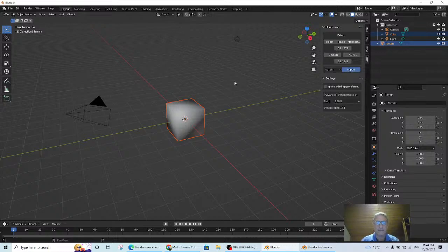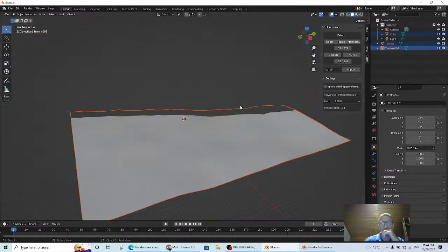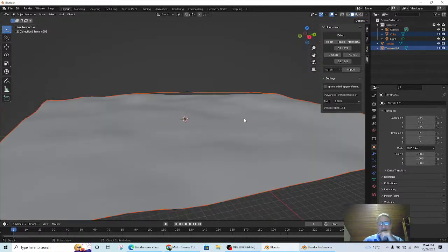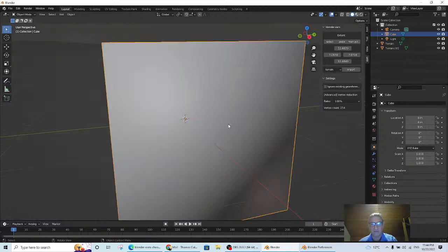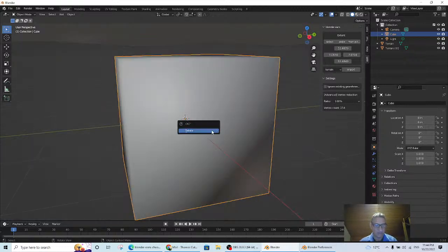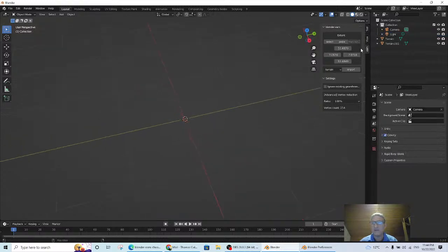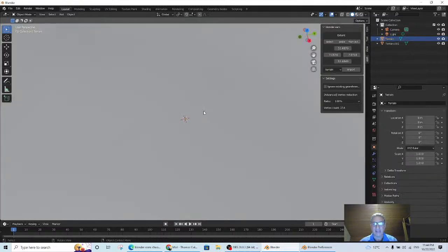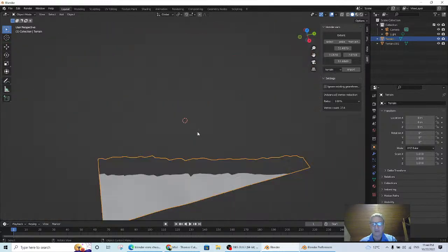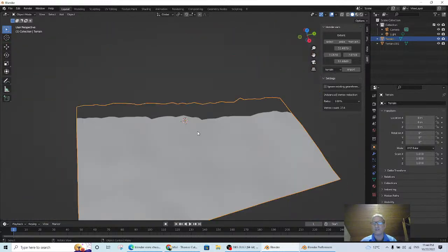And you wait, and the terrain should come in. You see it's spinning. So wait for the terrain to come in. Always start with the terrain. And it'll seem like after it stops spinning that nothing happened, but that's because the terrain came in way up there. Okay. So let me click over here on the right on the cube and hit period and come back to the cube. We don't need that cube, so I'm going to delete it. That's the end of the cube. You can see there is a terrain here, and when you hit delete, nothing, when you hit the period key, it disappears, and that's because of something called clipping.